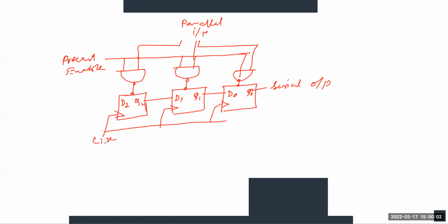Now in this shift register, we can apply the parallel input to each D flip flop by making the preset enable 1. So you already got that the preset enable is in the topmost position, and for every positive edge triggering of the clock signal, the data shifts from one stage to the next, and we will get the serial output from the rightmost D flip flop.